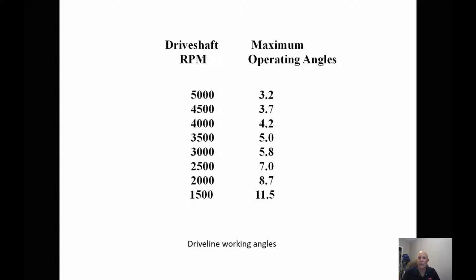Parts or components that start to wear out can also change the angle of the driveline. So if we end up with a vibration in the driveline, we want to be able to correct that. The problem may not be a problem with the transmission or differential. It might be something as simple as repairing the angles on the differentials or the transmission.